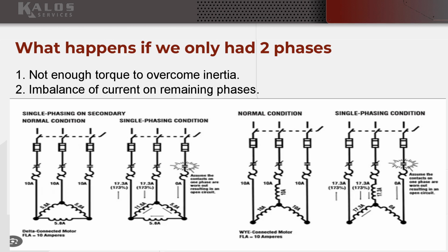Now, with a three-phase motor, even with single phase or three-phase, they both actually require 3 phases, and we're going to get into that. If it's a delta wound motor and it's already running, I believe it'll actually continue to run. It'll run less efficiently, and it might only run until the winding that is picking up the slack fails or the thermal overloads fail. It's called single phasing.